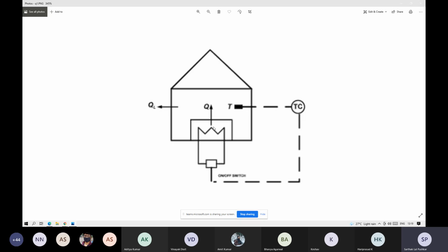There can be other possible sources of disturbance too, such as the outside door opening and closing, a loss of gas pressure, a change in outside temperature, or the outside wind velocity, which changes the external heat transfer coefficient. It could be windows that open, and also the number of people inside the room, each one generating and transmitting energy into the surrounding air, which can change the temperature of the home. And there can be electric lights and appliances of any nature being used inside.